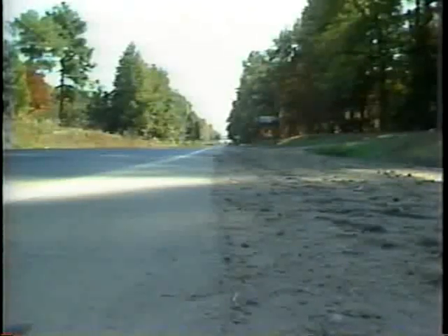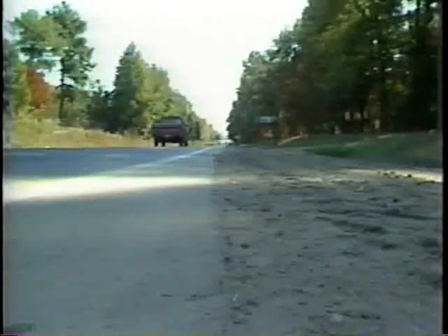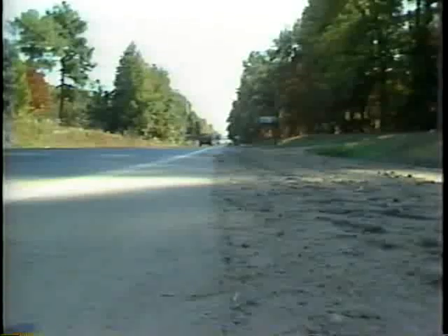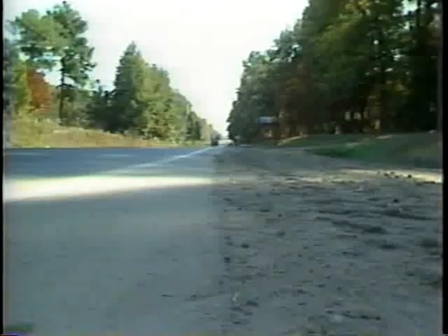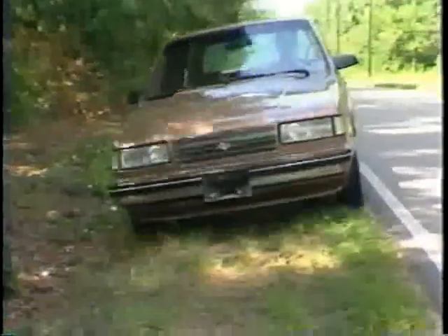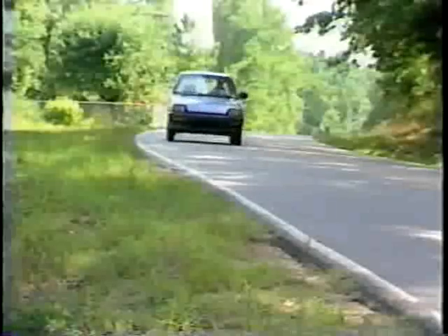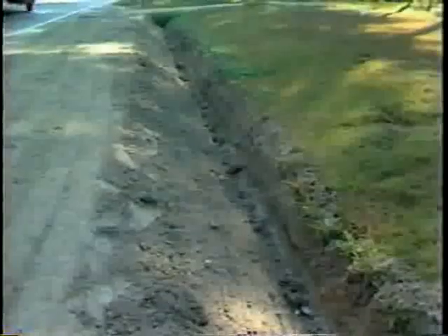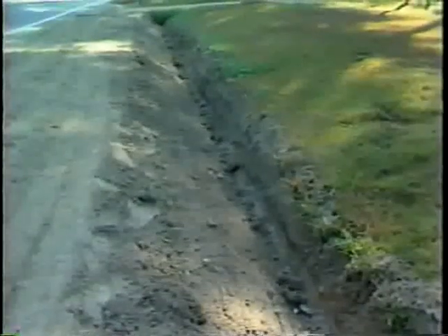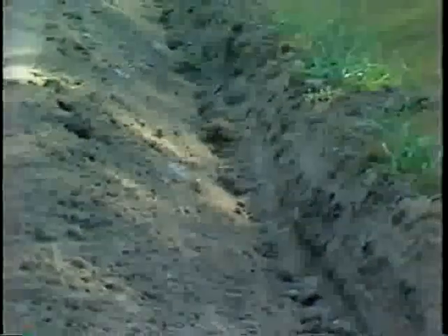The shoulder protects and gives lateral support to the pavement edge, base, and subgrade on each side of the road. The shoulder provides emergency stopping area for the traveling motorist. It also provides a recovery area for vehicles that may leave the road surface accidentally. And probably the most important function of the shoulder is to provide a surface to drain water from the pavement surface into the roadside ditches.